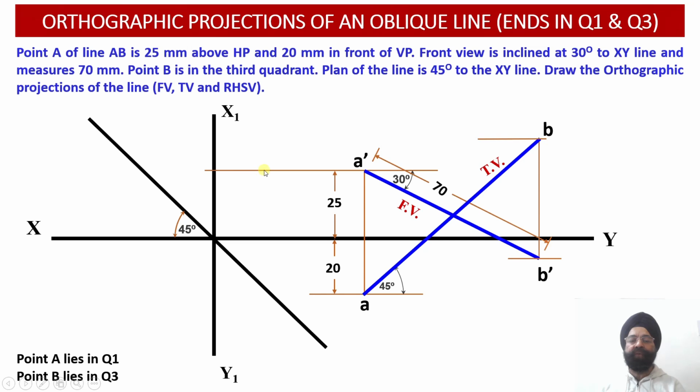So this height of the point A double dash has already been fixed as per the fundamentals of projections of a line. Now we have to transfer the distance of the end A in the plan view. This distance happens to be 20 millimeters, and it has to be transferred onto the profile plane projection.